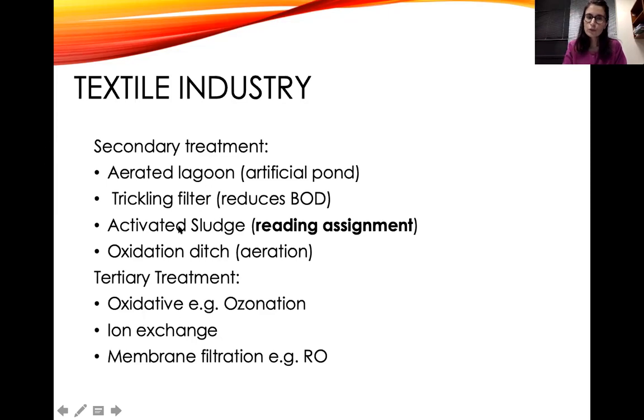And then all of these are basically just having septic tanks in the open air. So an aerated lagoon is just having that tank there. The trickling filter is a bed. We've discussed this before. You're just using a medium for wastewater to go through. There are bacteria there and they eat the nutrients. Slowly the water passes through and it has reduced the BOD remarkably.